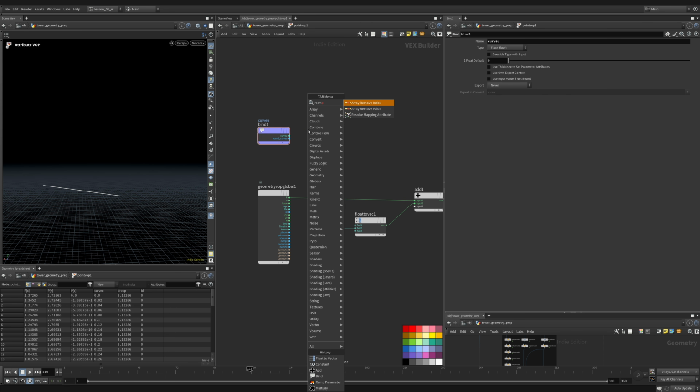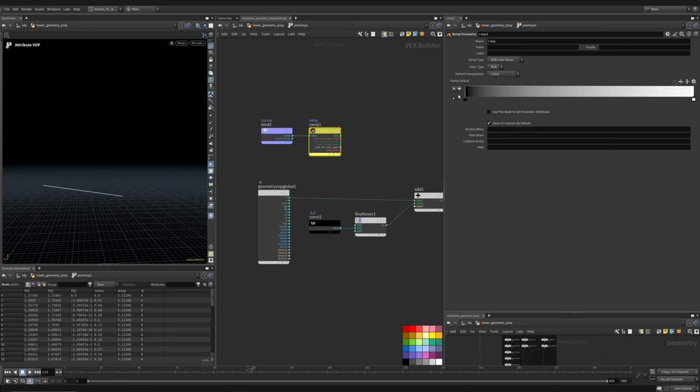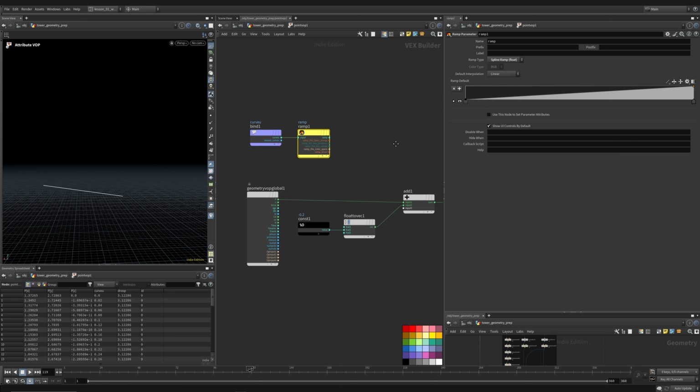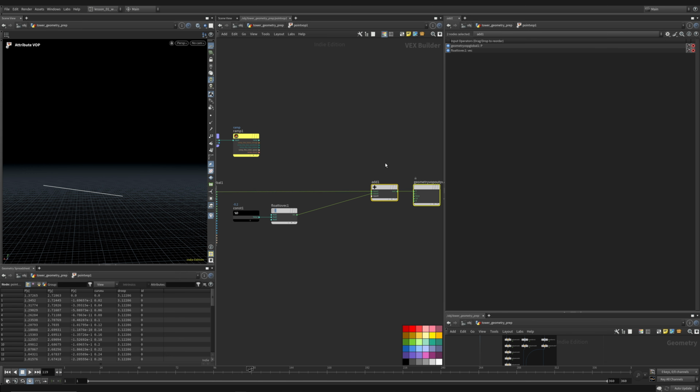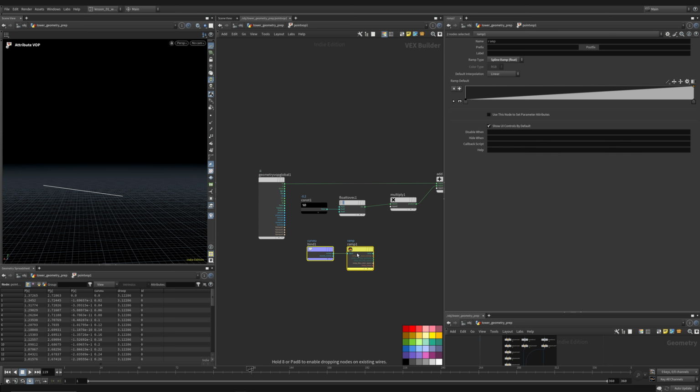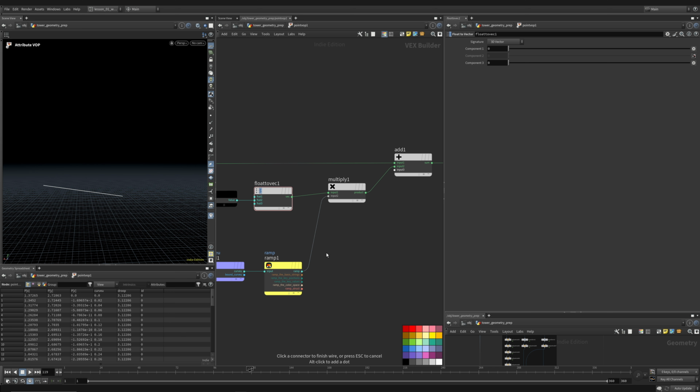So the way to do that is take a ramp parameter and bring that in here, a spline ramp. There are a few ways we could do that. We could displace every point and then lerp, or linearly interpolate, between those, but we're going to do it an easy way. We're just going to multiply the Y value we're adding by our ramp.